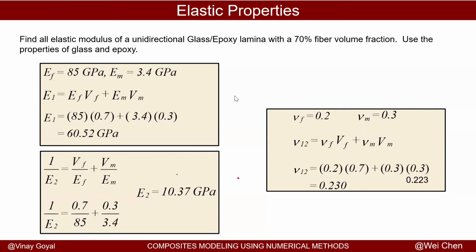So we can do an example here quickly, but for the same example I showed earlier, I can calculate the effective modulus in the one direction. I know the fiber modulus from specs and also the matrix modulus, so I can then determine the effective E11. So fairly simple process there. You can see the formula there.